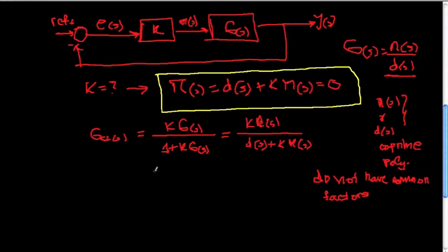And in this particular way, the finding of k has to assure that there is a range of k such that the closed loop system is stable. In other words, for fixed k, the closed loop characteristic polynomial will have certain poles. So this is imaginary, this is real, okay?